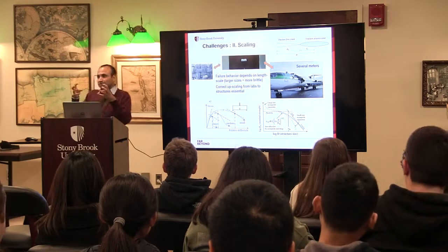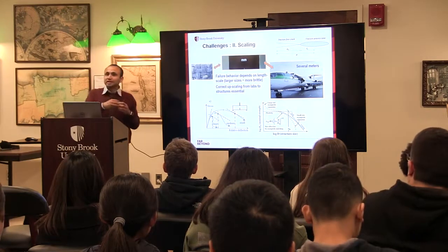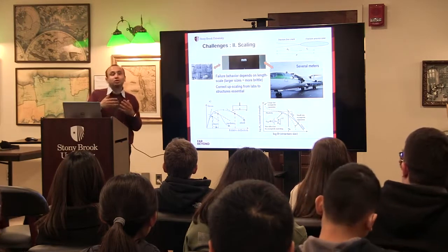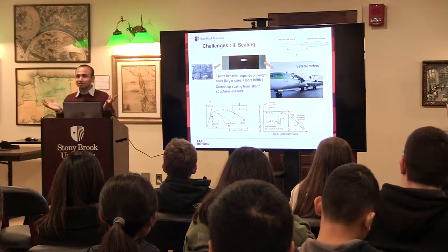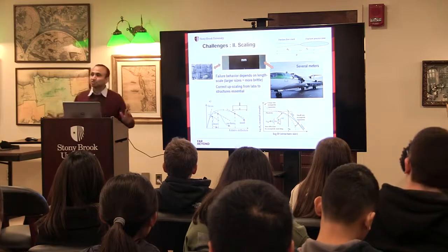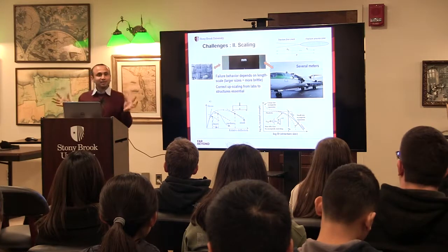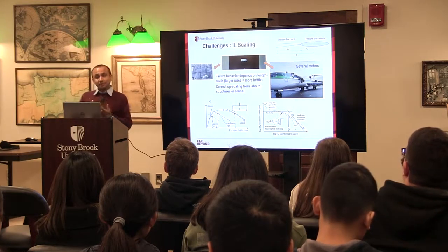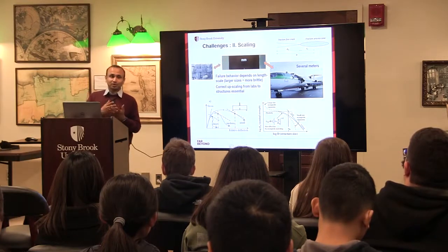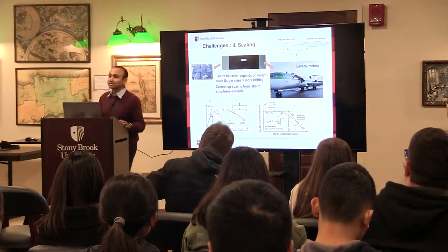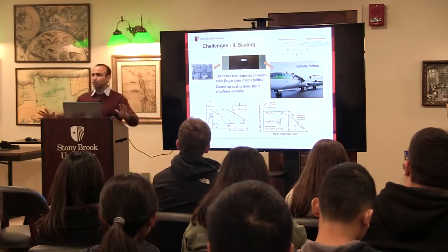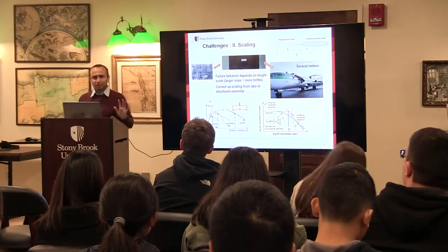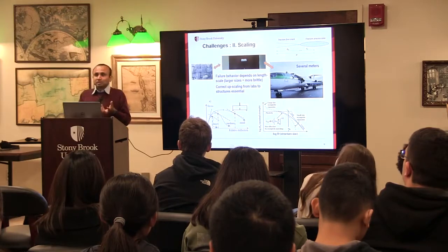And when you start making the specimen smaller and smaller, its fracturing becomes more ductile, more like a metal. If you are engineers, you take some course, this may be a little bit difficult to grasp. But for materials like composites, this does happen. So the failure behavior is size dependent. And there is actually a mechanics-based framework to analyze this. But we need to know this.